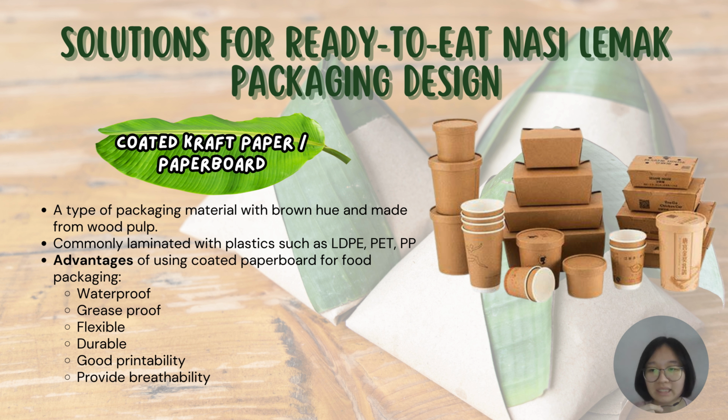However, paperboard itself is not waterproof and can wear off easily when wet, hence unsuitable for food with high moisture content like nasi lemak. Therefore, paperboard used in the food industry are commonly coated with plastic films through extrusion or adhesive lamination to enhance the packaging effectiveness. Plastic films such as LDPE, PET, and PP aid to improve the paperboard's resistance towards moisture and oil or grease without compromising the flexibility of the material.